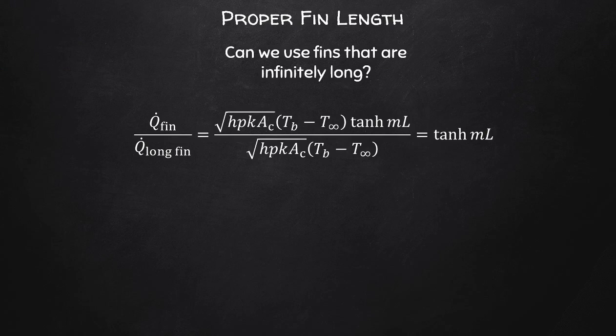Okay, so just think about, remember what M refers to. Think about what happens with M and also M times L if we increase the length more and more. So, the question really becomes, can we design fins that are really, really long? What is the effect on efficiency?